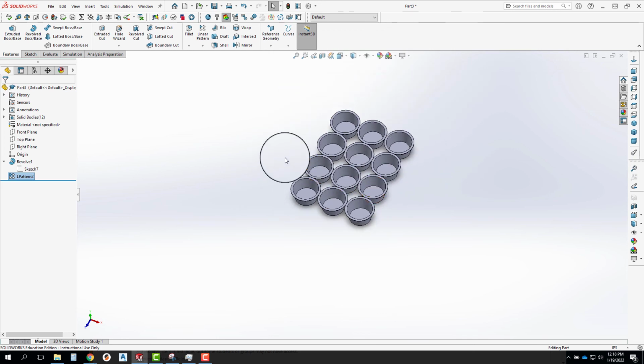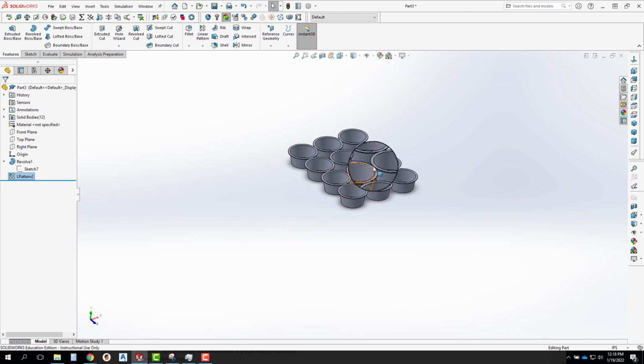So hopefully that's helpful as 3 different ways we could create the same part. I think probably the fastest, cleanest, and simplest one was the first way I did it, where I extruded a tapered puck, shelled out the inside, created a pattern of that body, and then added the sheet that was going to be the top. Hope that helps.